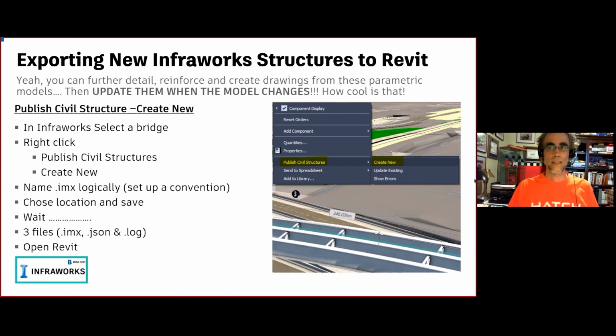We still need drawings. What I like about this process is that these models and drawings in Revit are tied all the way back to the corridor through InfoWorks. It's all tied back to that corridor, and the adjustments happen as you make changes along the way.